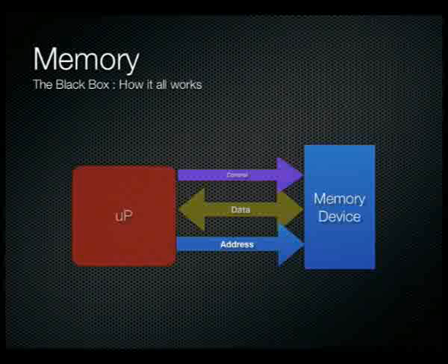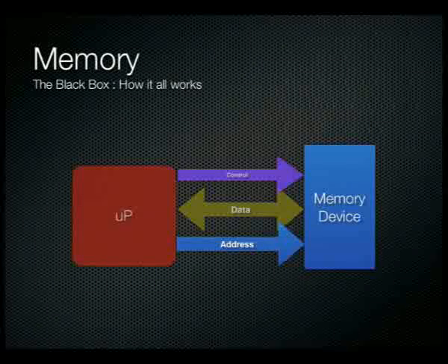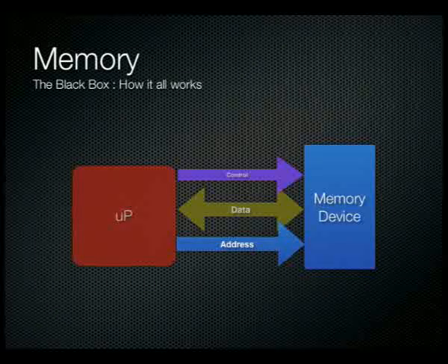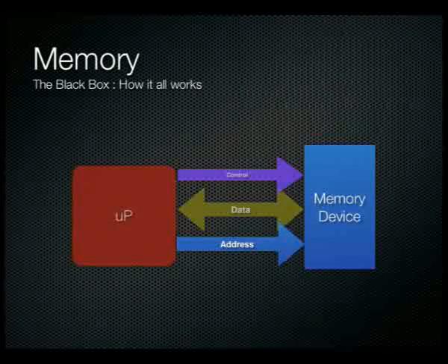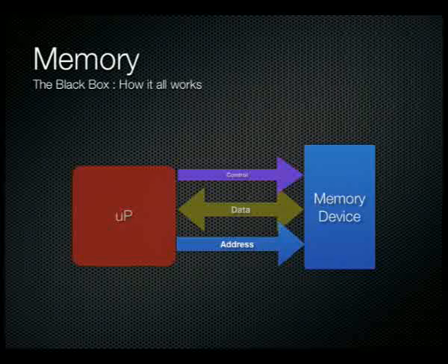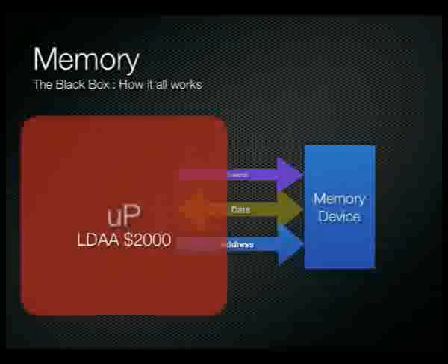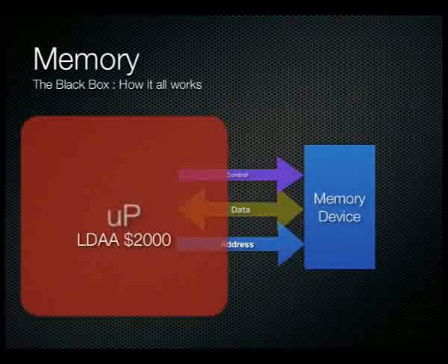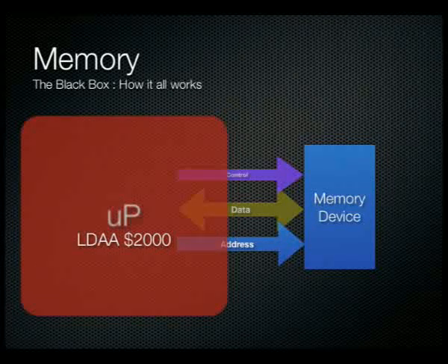Okay, so just in a nutshell, how is it that memory works? To give you an example, I've got a little animation here to show you how a memory transaction would take place when we're trying to read a particular value out of a memory device. Inside our microprocessor we have a command that we're going to run, and this command simply wants to load accumulator A with the memory location 2000. So whatever the contents of the memory location 2000 are, we want to load them into the microprocessor.